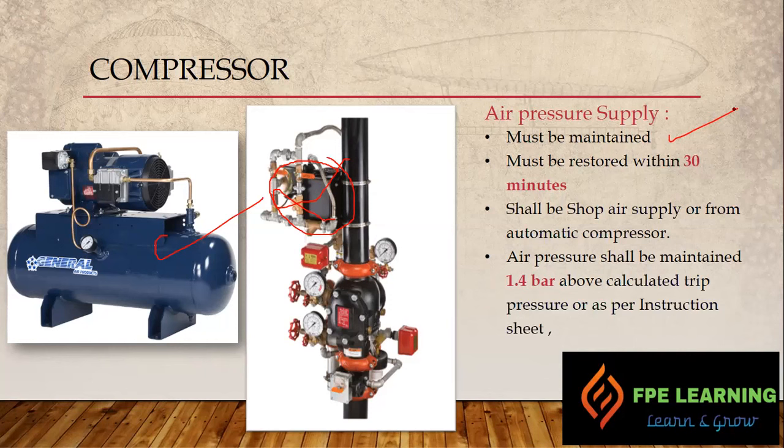And how you are going to pipe, I have not covered that one in this module. You can go to 7.2.3 of NFPA 13, which is the size of the system. Normally they have given a table, right? Based on the table, they want to make sure for 1 foot of the pipe, what is the capacity in gallons or liters. You can find that one.